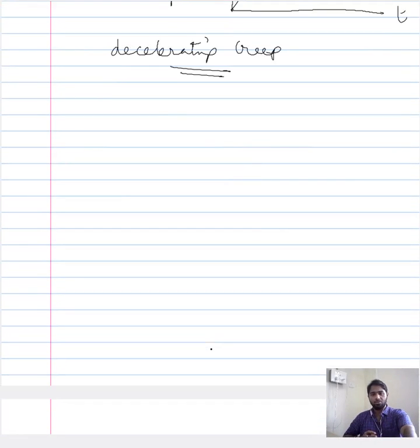Now, whenever there is a dislocation that is being formed in the system, with increase in the load or with continual plastic deformation, there is an increase in the dislocation density. When we talk about this increase in the dislocation density in terms of the overall energy of the system, there is a proportional increase in the overall energy of the system.